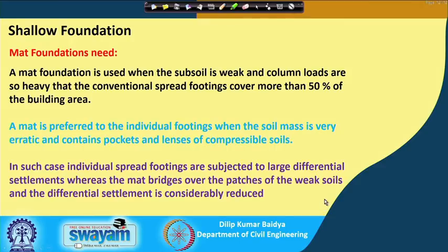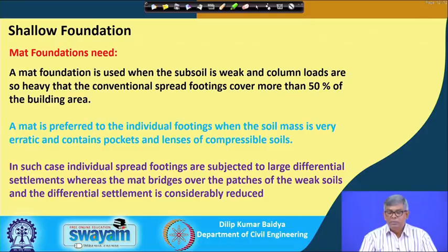Let me see the need for mat foundation. Okay. Mat foundation is used when the subsoil is weak and column loads are so heavy that conventional spread footings would cover more than 50% of the building area.